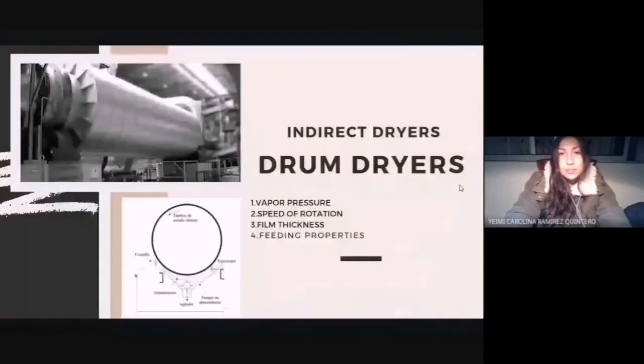Okay, the first type is the drum dryer. This type of dryer allows high drying speeds and economy in the use of heat. However, this type can only be applied to liquid substances or in the form of slurry capable of withstanding relatively high temperatures for short times, from 2 to 30 seconds.